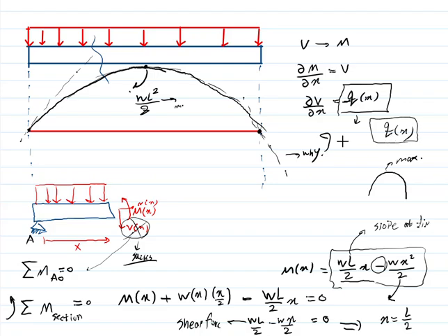So it's actually not a weird thing, but it's the way you draw the diagrams that defines this minus. If you put the positive upside and the negative downside, you must have this minus for things to add up correctly. But if you have a way of showing positive moments below the line and negative upward, some of the engineers will do it because it is actually easier for technical works. We do that actually. Do you know why?